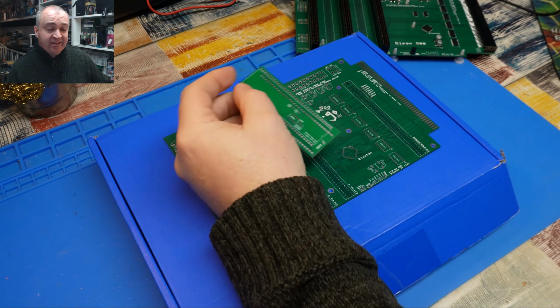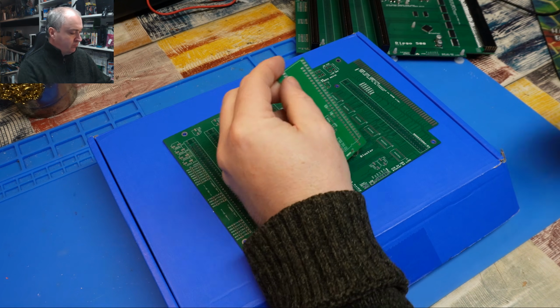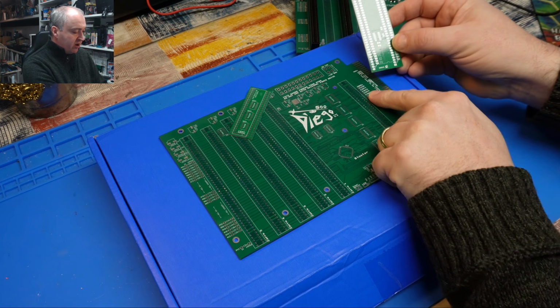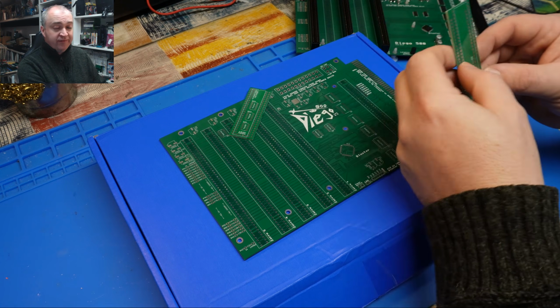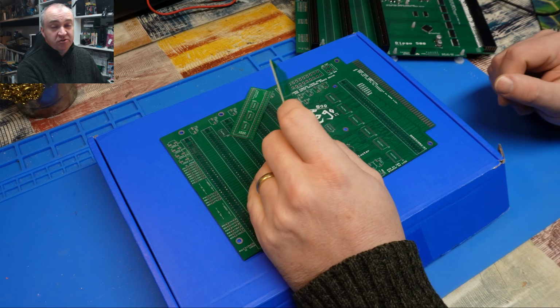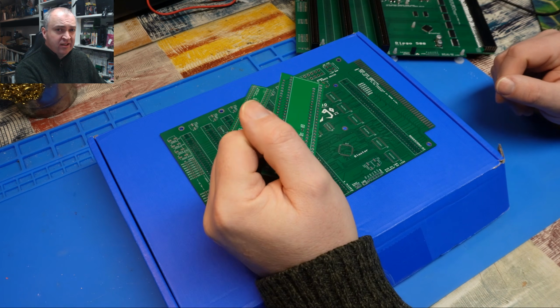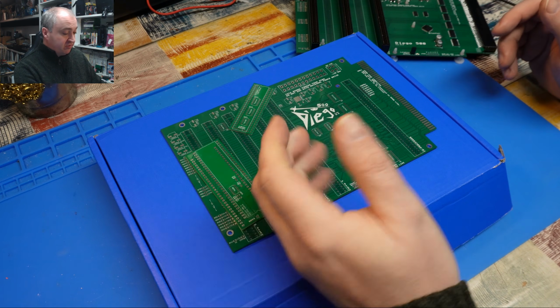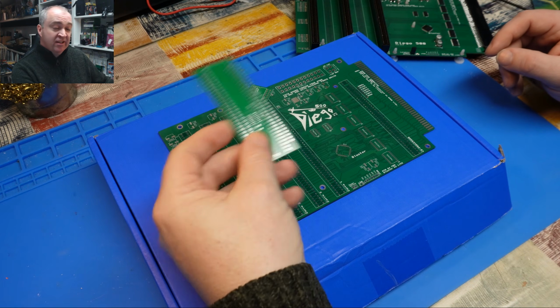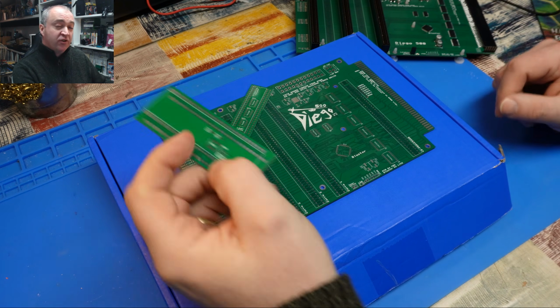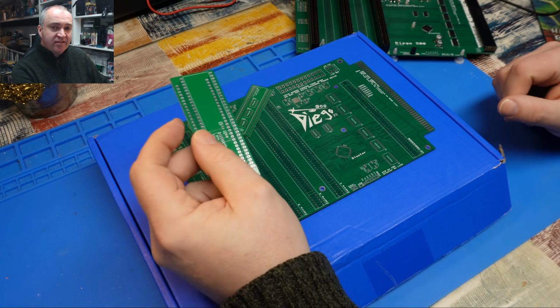This will sit in line with the internal CPU. Your bus connection needs to be wired from there to there. There's a 7408 to fit, and that reintroduces that bit of missing logic. Of course, the other solution to it is just remove the internal CPU, but I wanted to provide this option for this functionality here, just to try and make the thing complete.